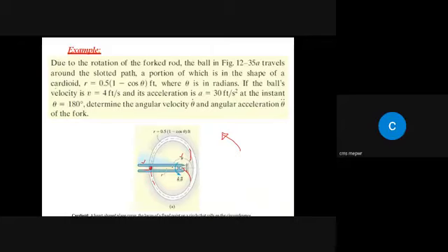You can see the radius r, the position of this ball from the fixed point. It is not constant now; it changes at every instant, and it is given by this equation. At angle equal to 0, cos 0 is 1, 1 minus 1 is 0, so r will be 0. It will be at this fixed position. For example, at cos 90, this becomes 1 minus 0, and this becomes 0.5. So at 90 degrees, r will be equal to 0.5. Right?